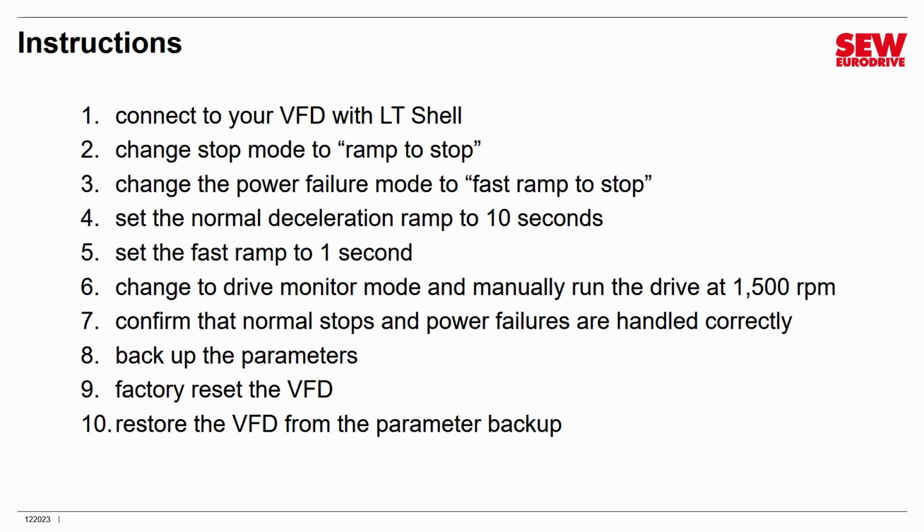I'd like you, first of all, to get connected to your VFD with LT Shell, so you'll need to get your cables hooked up, load LT Shell into your PC, and then, of course, fire it up. Scan into your network and see if you can access your VFD. Once you've done that, you'll go into parameter edit mode, and I'd like you to do these things. I'd like you to change the regular stop mode to ramp to stop. I'd like you to change the power failure mode to fast ramp to stop. Set the normal deceleration ramp time to 10 seconds. Set the fast ramp time to 1 second.